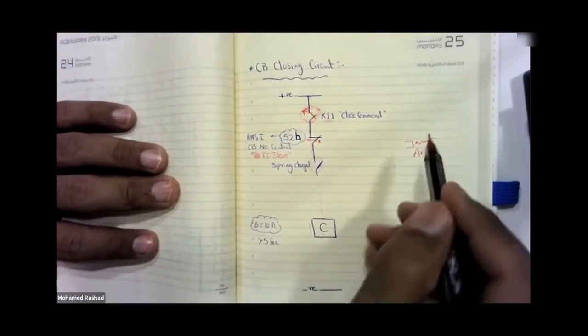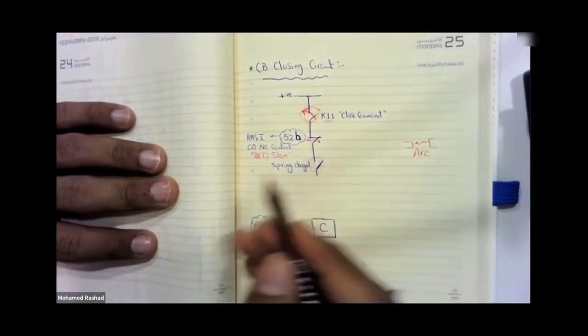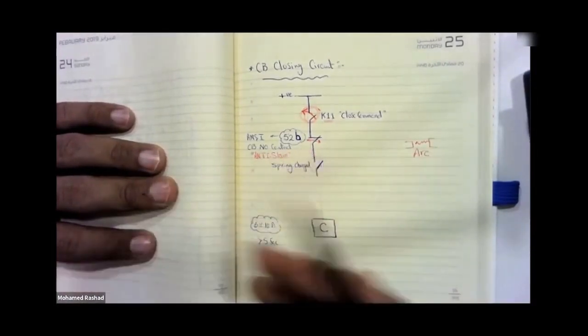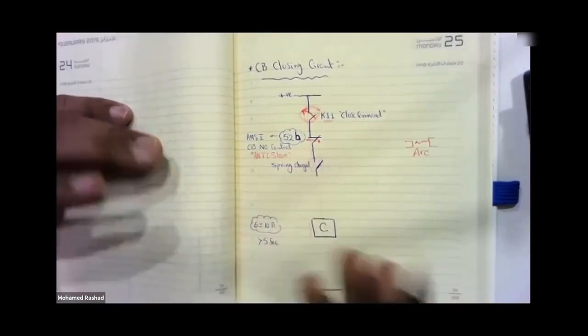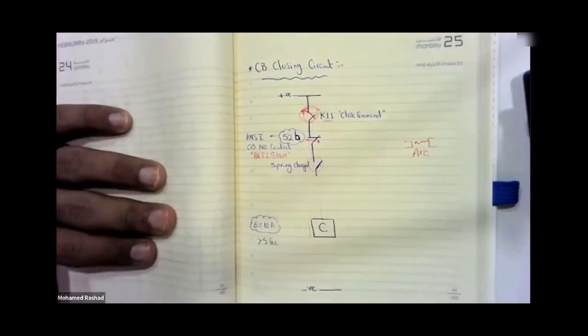So of course, this is wrong mechanically and electrically due to the presence of the arc. In addition to the frequent arcing every 10 seconds, the SF6 gas will naturally start to heat up and decompose. So, of course, you're not giving it a chance to recover. The SF6 gas might lose its insulating properties. So what am I going to do to solve this problem?